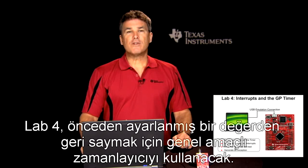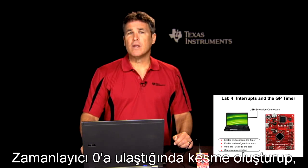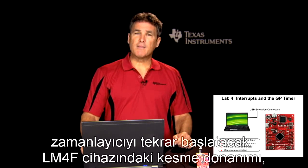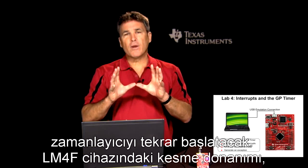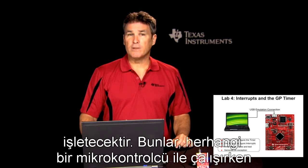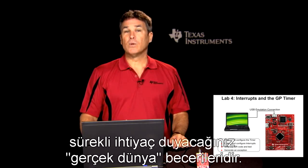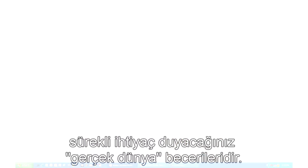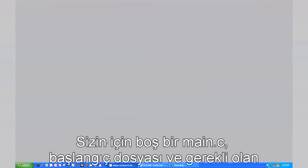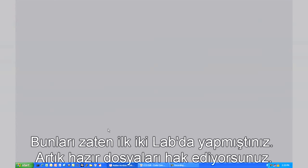Lab 4 will use the general purpose timer to count down from a preset value. When the timer reaches 0, it will generate an interrupt and reload the timer. The interrupt hardware on the LM4F device will then find the correct address of the interrupt service routine you've written and execute it. These are all real-world skills that you'll need over and over again when working with any microcontroller. We've already created the Lab 4 project for you with an empty main.c, a startup file, and all the necessary project and build options set. You already paid your dues, you did that in the first 2 labs.